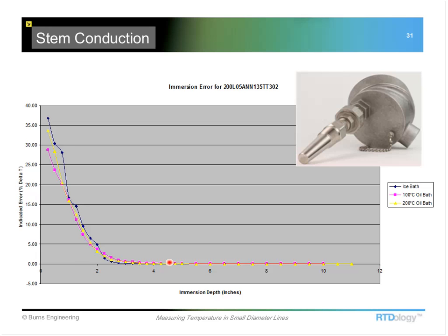And so for this type of assembly, 4.5 inches is a good minimum number to use. Now that doesn't mean that you can't use smaller immersions, but to get rid of this error, like in a standard 2.5-inch immersion thermowell, whether it's a threaded industrial style well, or a sanitary well that maybe has a tri-clamp connection on it.